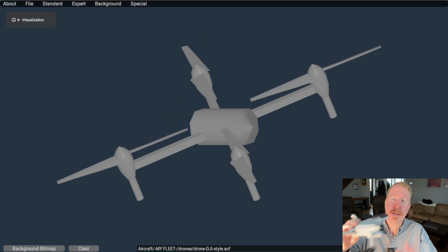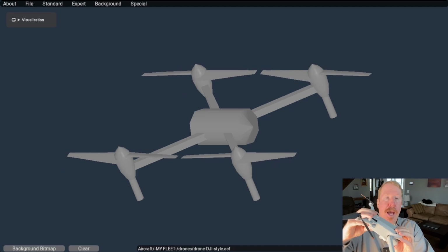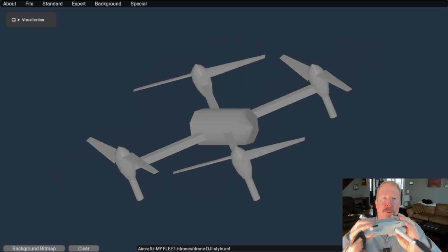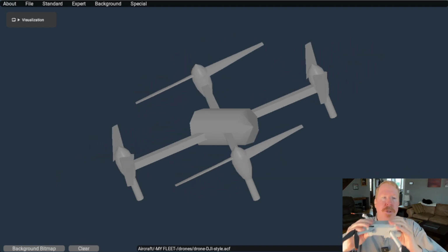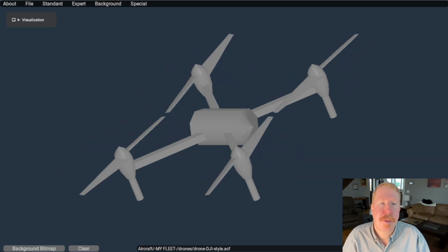Another thing we've been looking at a lot is roll rates and pitch rates. When I'm inside an airplane, I'm perfectly happy to control the airplane based on the pitch rate and the roll rate and the yaw rate. The problem is, with these drones, if you command just a little bit of a roll rate and it stays in there, eventually you roll the thing upside down.